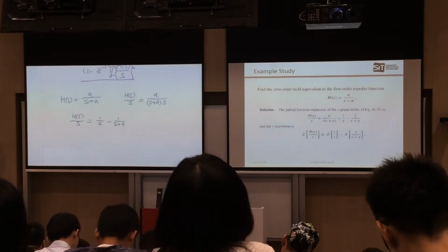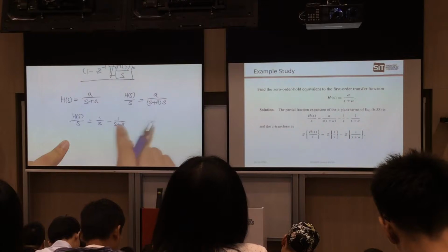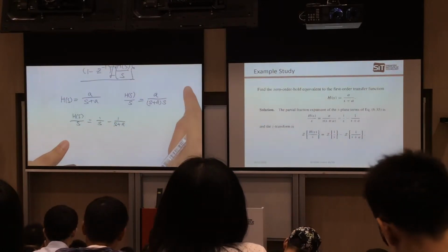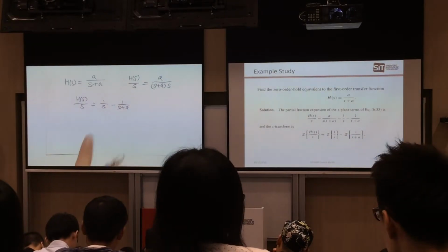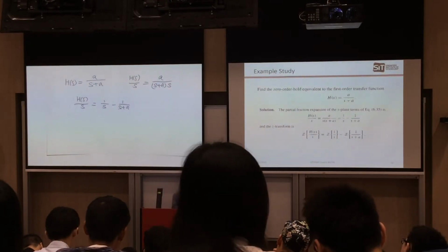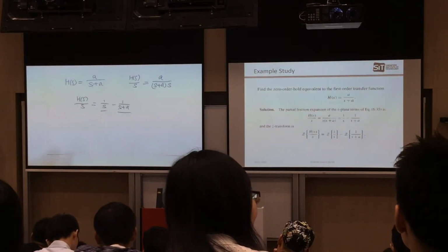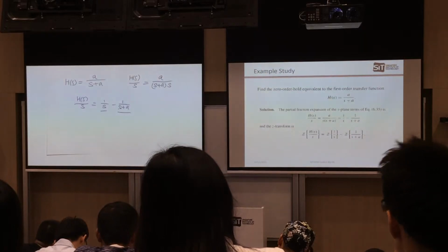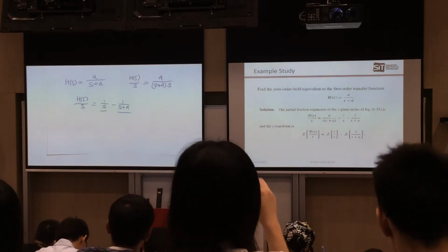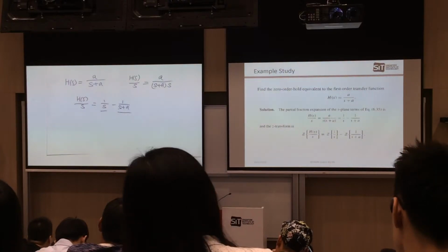Okay, if you don't know how to do it, a simple way is you take this A minus this B, right? Then you find the equivalence of your A and B. Okay? But to solve, I have just solved already. Okay, this one. So after you get this, then what do you have to do? Do the inverse Laplace transform, then sampling, then do the Z transform. But in practice, it's very simple. Look at the table, right?